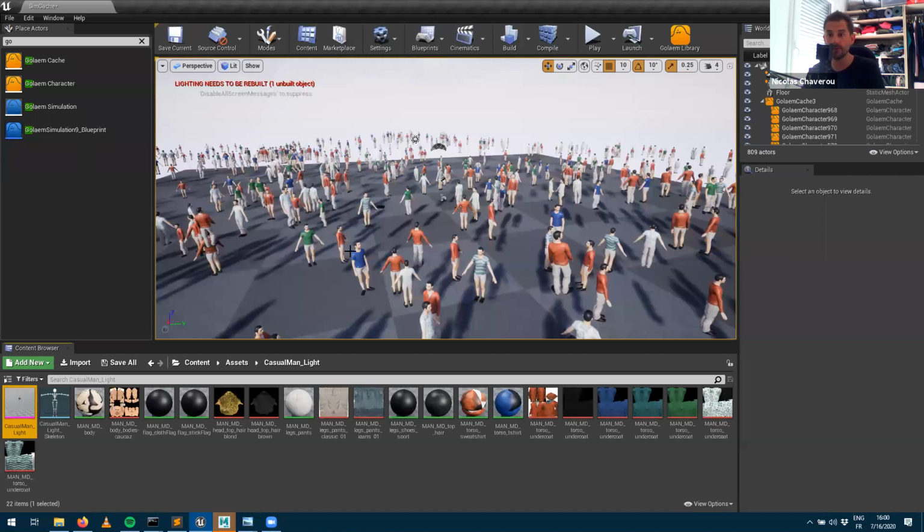But obviously we do support blend shapes, and we support bones for facials. One casual rig that you can do is probably one bone for the jaw that you can control with just orientations, and put blend shapes maybe for the blinks and the facial stuff. It's fully integrated. The blend shapes are like any bone. They're just animation channels, so we record them along with the animations and blend them as well. You can also use procedural animations to do some automatic blinking when you need it, and connect that to whatever you want with expressions. So yeah, it's fully controllable.